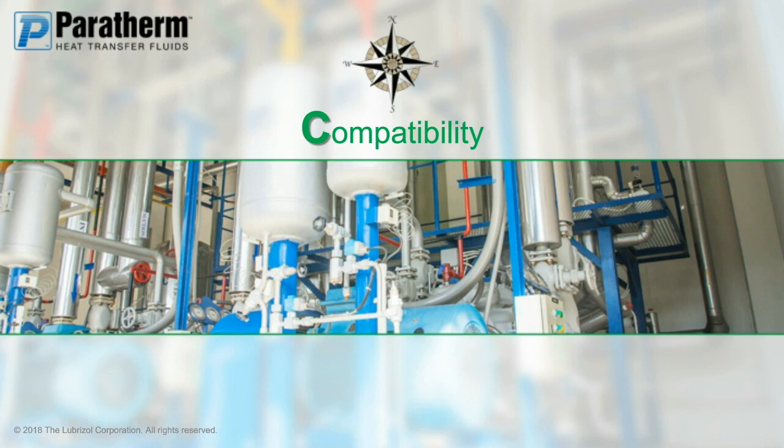Key point here with aqueous fluids, you want to make sure that there's no dissimilar metals that come in contact. The galvanization process, when you're looking at aqueous fluids, that's a serious concern for causing corrosion in those kind of systems. But even more, one area that you really need to look at with the non-aqueous fluids, the polymers, seals, gaskets, etc., need to be rated, 1, for the temperature that you're looking at, and 2, for the fluid that you're putting into that system.